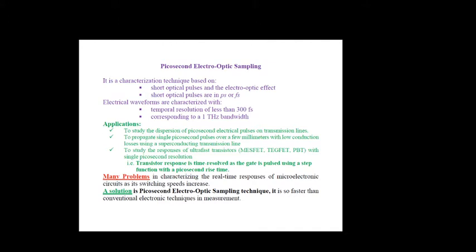Their responses have been studied by means of this evolving electro-optic sampling technique, and switching times as low as 5 picoseconds have been directly measured for the PBT, the permeable base transistors.